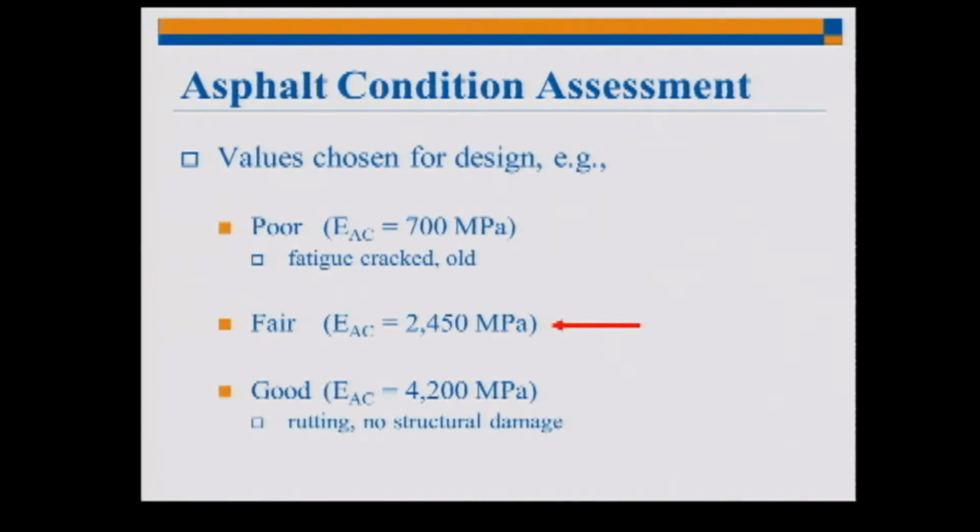Generally, we make some assumptions on the asphalt. You can't go out and do extensive testing on all the projects because the asphalt stiffness is going to change as a function of time and temperature. And so we generally assume some type of fair condition in our state. If you had a different state or a different climate condition, you'd probably assume a different value.